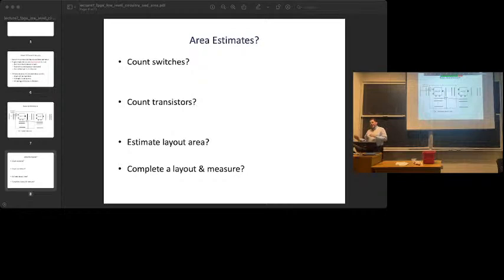The ASIC CAD tools are built around standard cells. Okay, so don't do transistor level optimization. The transistors have already been grouped into a flip-flop, an AND gate, a MUX. And they're in what are called safe circuit styles, like safe CMOS styles where you can combine those gates together and they always work. You can build an FPGA that way. And if you do that, there are actually automatic tools that will do it for you. They wind up with an FPGA that's typically 2 to 3 times bigger and 2 times slower than if you had done it with full custom design the way I'm going to show you.